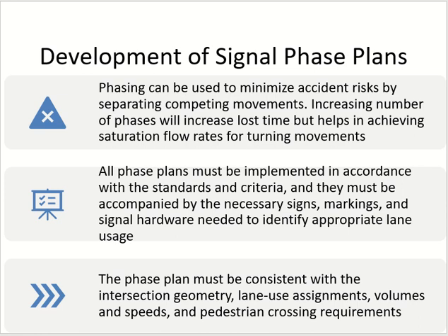So there is no fixed phasing plan that you have to do this, this, this. It depends upon you. They are only guidelines. If you follow the guidelines, then whatever plan you have is good. Got it? So there is no fixed phasing plan. Clear? So I'll just give you the guidelines. The first guideline, already mentioned, is that the phasing plan should be safe. Okay, conflicting movements cannot happen in the same phase.